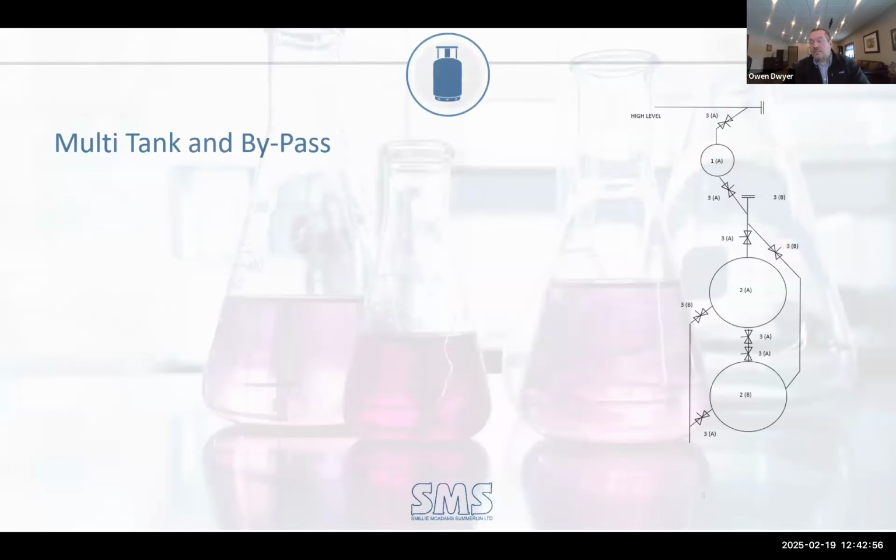These tanks are not off the shelf typically. So when you specify something, it's important to put your detail in your spec, the diameter, the height. If you can, specify your functional capacity, or at least spell it out, all of the detail in your spec. So your diameter, your height, your volume, your functional capacity, fixture unit capabilities, et cetera. All of this will help make sure that you're getting the correct tank for your project.